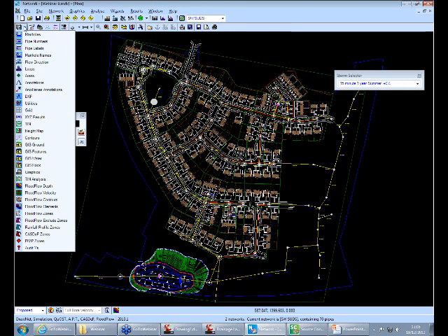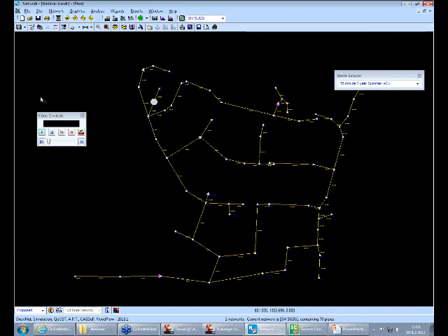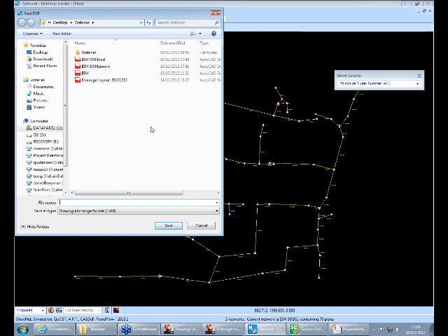So clicking on the view options drop down, I'll come down and switch off things like the drawing image. I'll turn off the DXF, and there we are. We're now back to just what we're showing in the window, the stormwater sustainable drainage system. At the top toolbar here I can click on Save DXF, and I can save out in a DXF or DWG, just a drawing format. I'd just type in a file name here, so you could go for BIM, stormwater, or whatever, and save that out.